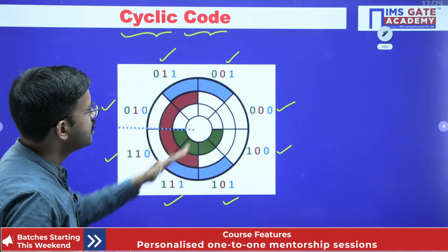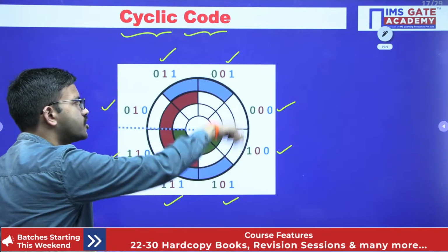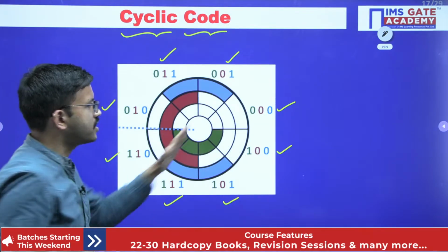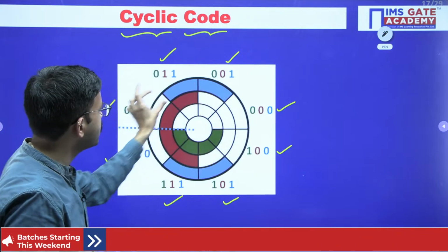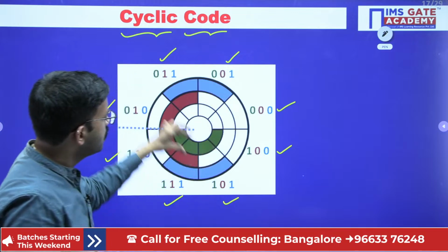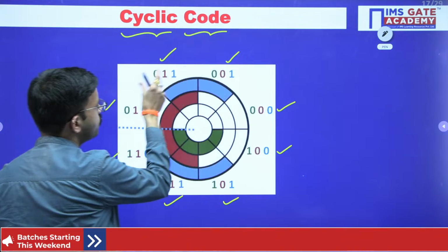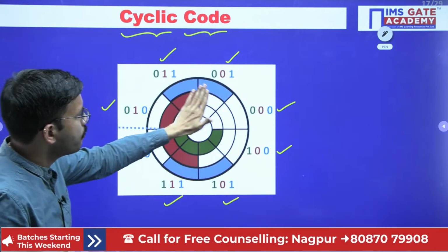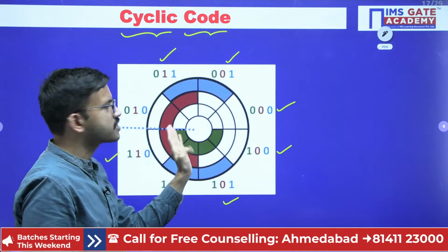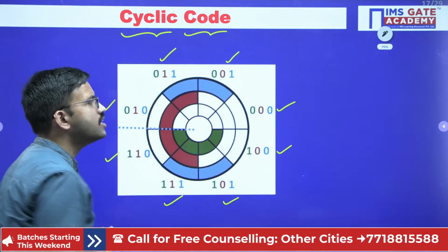You can observe here, while you are moving from one sector to another sector. See, here you have one circular shape. This circular shape, for the time being, I have partitioned into 8 parts. That means you are getting 8 sectors, right? From each sector you will get some angle. So each sector you can represent with the help of one gray code like this. Since I have made it into 8 parts, I have used the 3-bit gray code. Similarly, if you want to make 16 parts, at that time you require 4 bits. Based on the requirement, you can place the gray code.